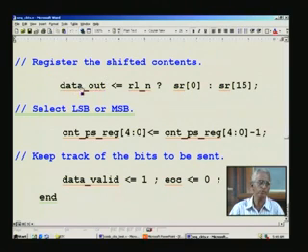Mind you, data out is only a single-bit output as such. On the other hand, if it were left shift, that is, this will be deasserted, logic 0, low, and then in this case we have to send the MSB out. That is what is being done here, and having done this, you have to decrement the counter that we had, which keeps track of the number of bits sent.